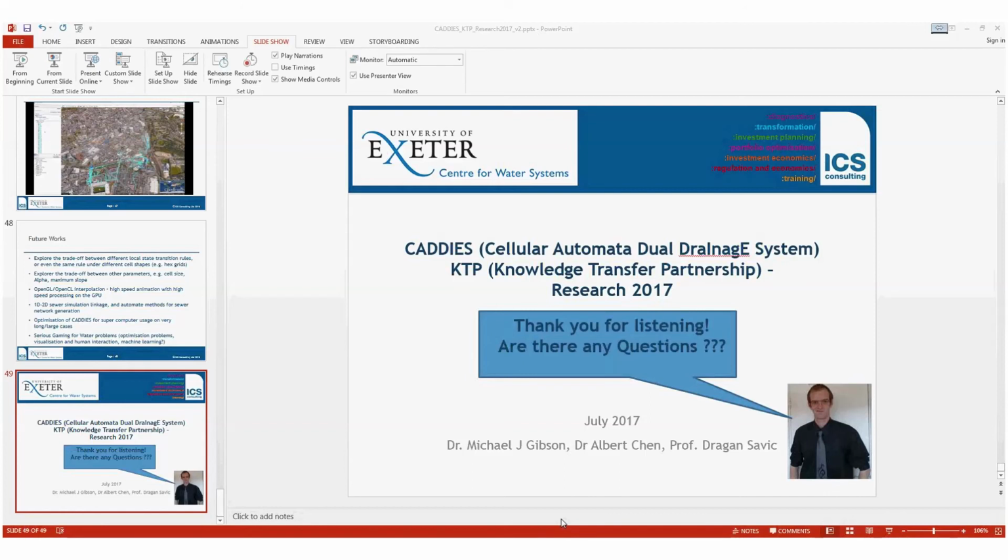Thank you. And have you considered soil characteristics in this modeling? How do you consider it? Because I'm asking, for example, if you have a huge area of sand parking lot near the pipe burst, it can absorb the water, and it cannot go further into the other neighborhood areas. I wanted to see, have you considered soil characteristics in the area? How did you do it? Yes, the CADDIES model can consider what we call infiltration, so have a water absorption rate per cell. So it's just a case of supplying that data then to the soil characteristics.